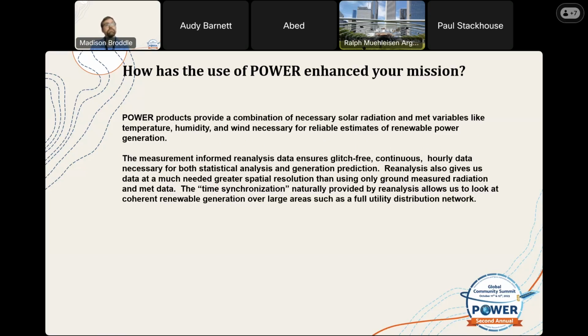So I can develop a solution that says, what's the 99.5% chance that I'm going to be able to power through this outage of 7 days at this military base with a given size of solar and given size of storage given a load? That's the sort of numbers that they want to know. They don't want to know, well, okay, 50% chance using TMY data, maybe I used an extreme year, but that still didn't include the 7 most cloudy days that could have happened.